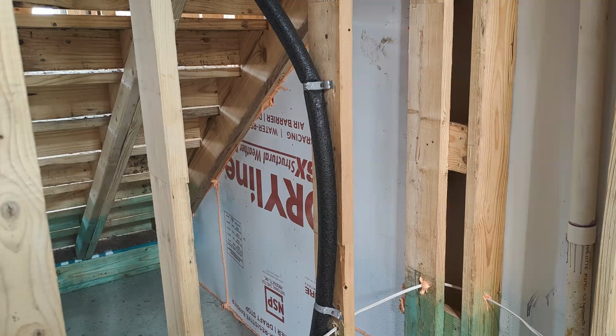creating an interior air barrier. Now that you've been asked to build things in front of the walls like staircases or chases or anything like that, where you're going to remove the interior air barrier and build the structure, now that interior air barrier must be reinstalled and sealed after the new things are attached to the exterior wall or garage wall. These include staircases, duct chases, under tubs and showers, and under water heater platforms and decks. So both the exterior and interior air barrier must exist.